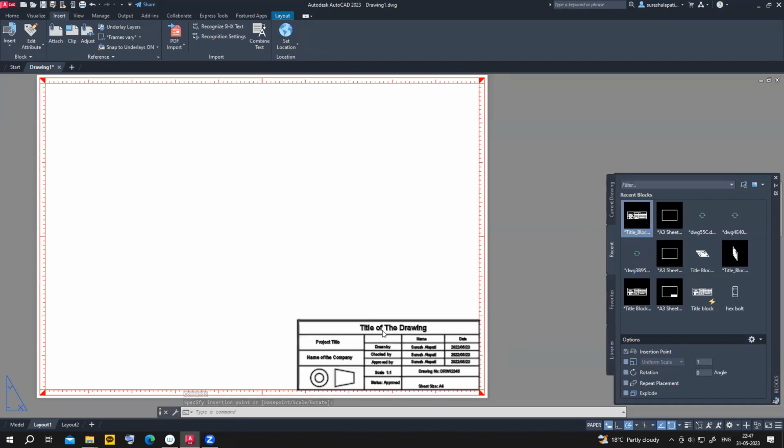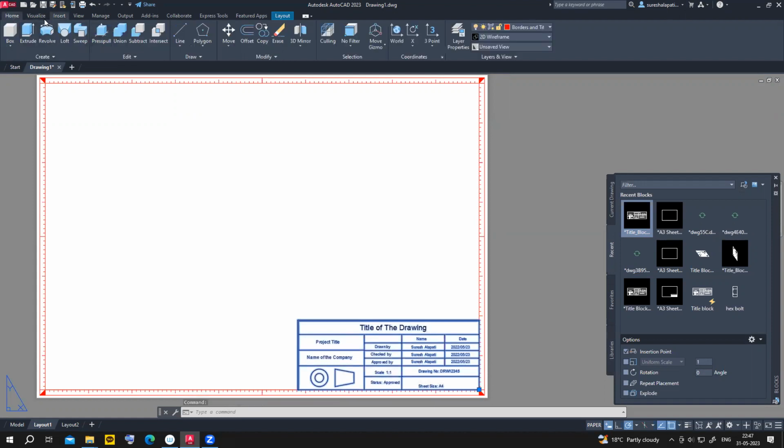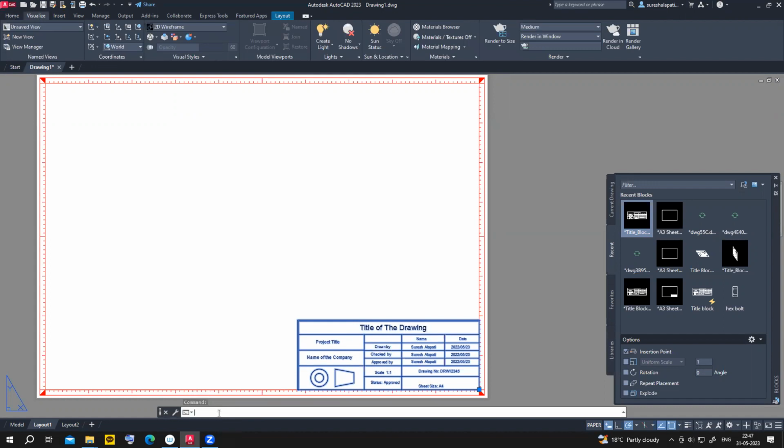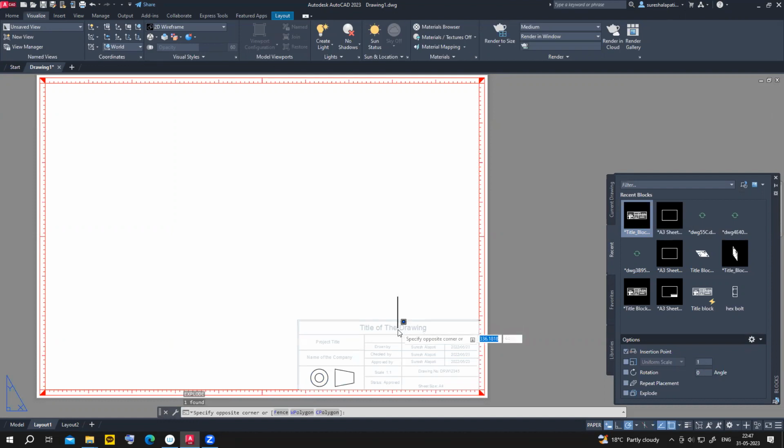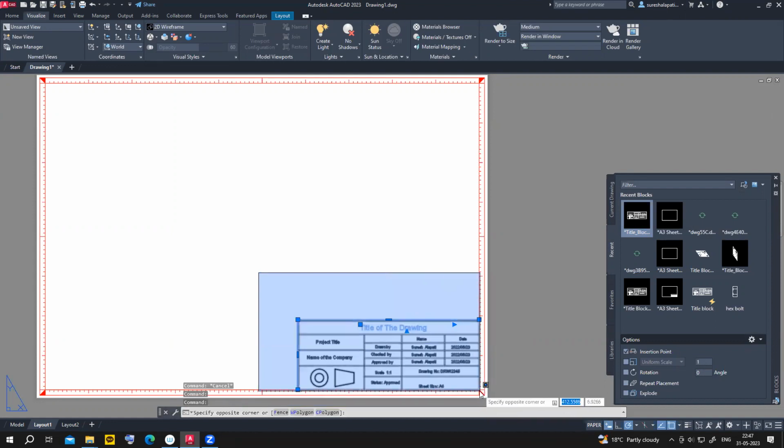To change the title of the drawing, I cannot change this one, because this one is now an entire block. Explode that block. Type explode, or go to drafting and annotations. Explode means making the things separate. Enter. So explode it. Now the entire thing is changed.